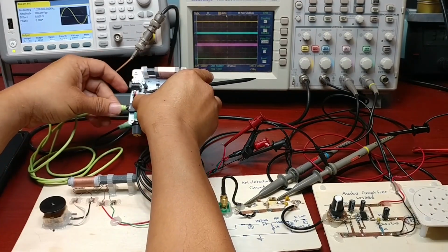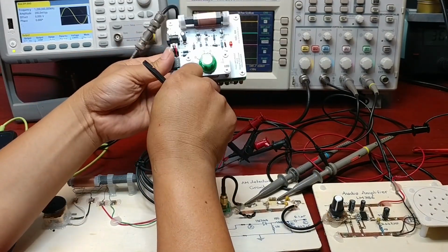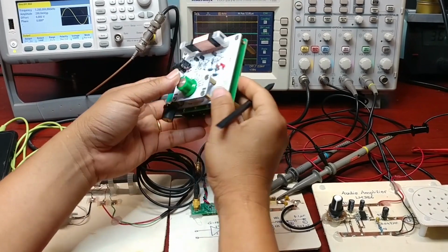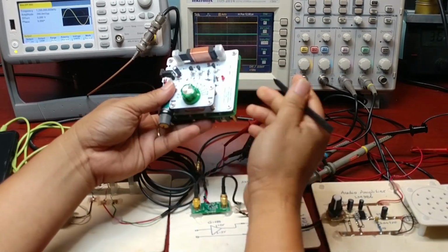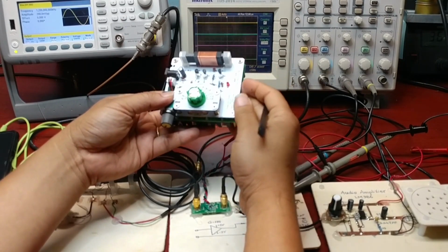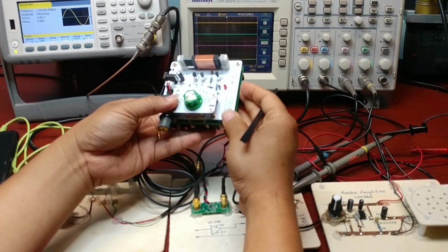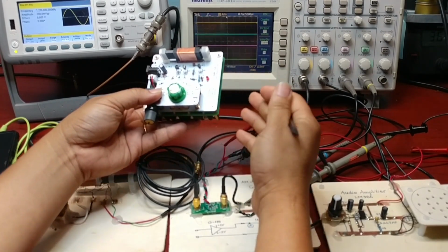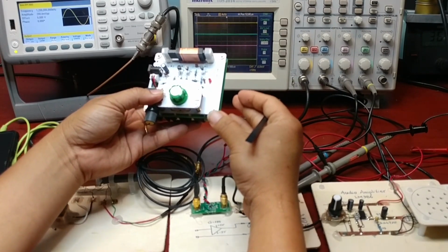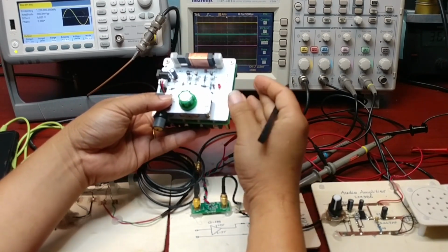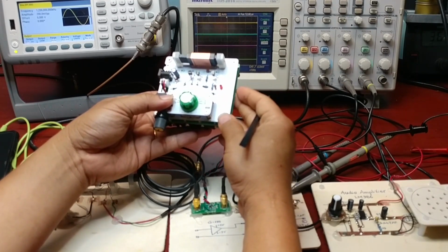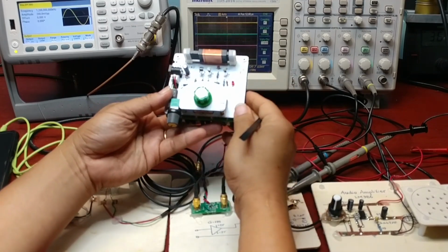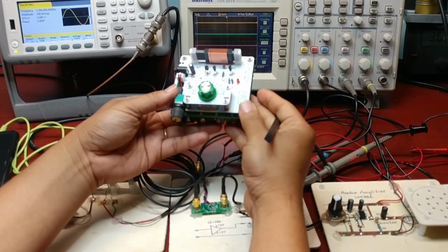I've shared with you the AM radio signal from the transmitter to the receiver. I'd like to talk a little bit about this transmitter. This transmitter is different from a regular AM transmitter of a broadcast radio station. This transmitter can only transmit magnetic fields. The transmitter of a radio broadcast station can transmit electric and magnetic fields. The electric and magnetic fields combined can carry the carrier frequency very far. And the transmitter of a radio station needs a very tall antenna for the AM band. This transmitter can only transmit a magnetic field, and the longest distance it can reach is about 1 meter.